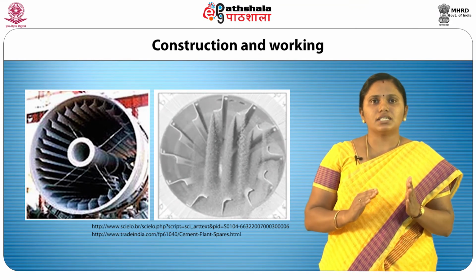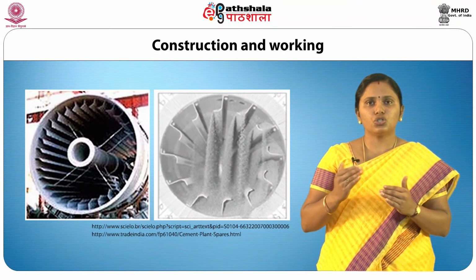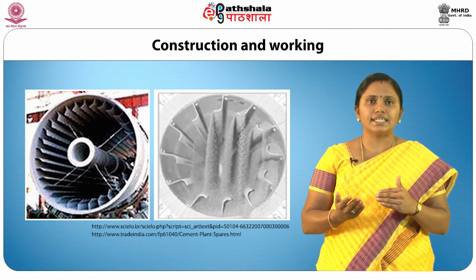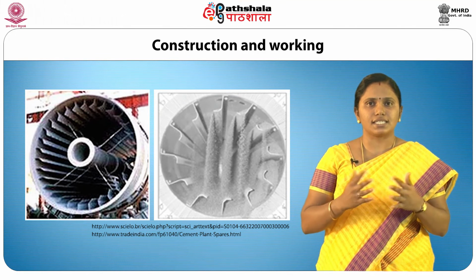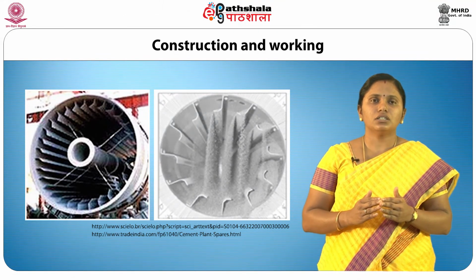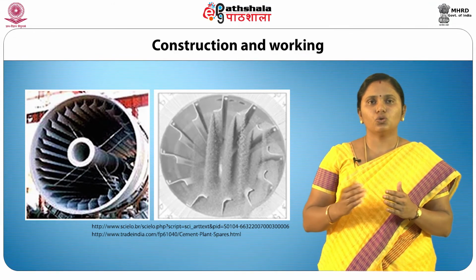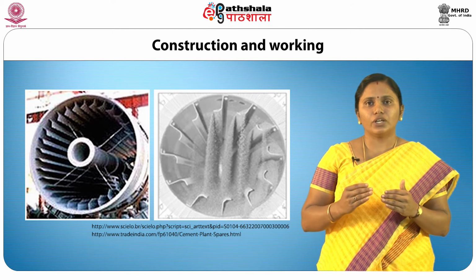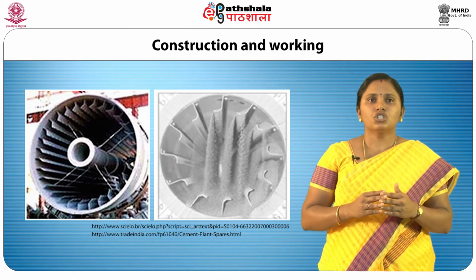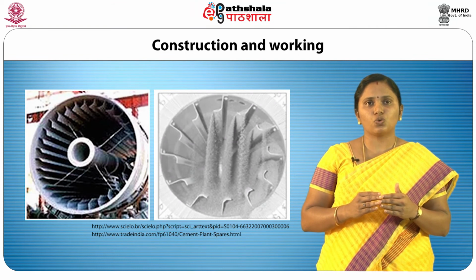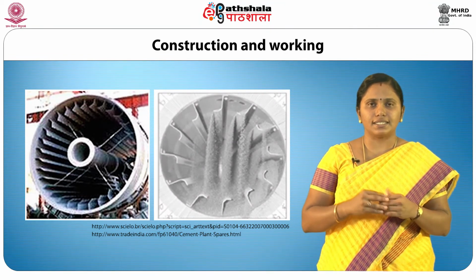This arrangement helps the material not to dust and hence is more useful for those materials which have a tendency to dust. Air temperatures of 120 to 175 degrees Celsius are usually used, and air velocities ranging from 2000 to 25,000 kilograms per meter square per hour are used for coarse particles.